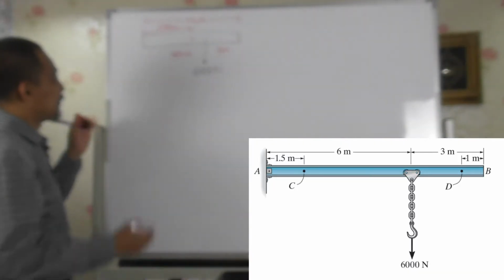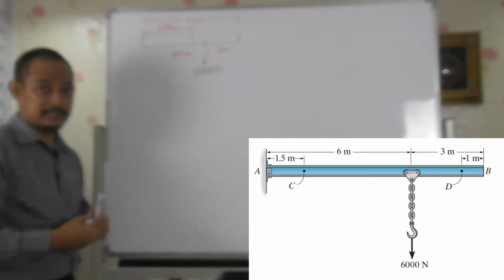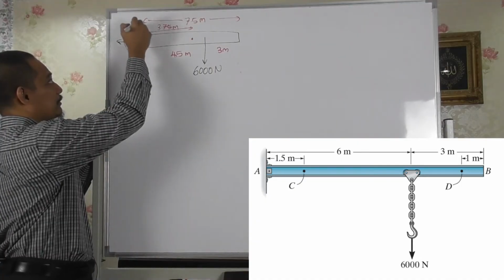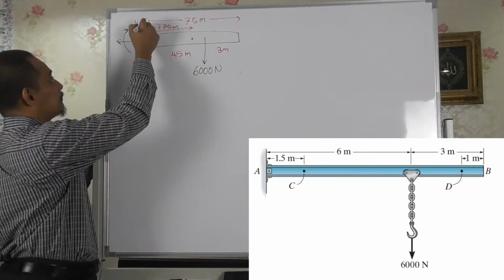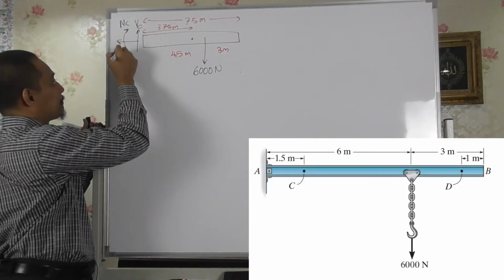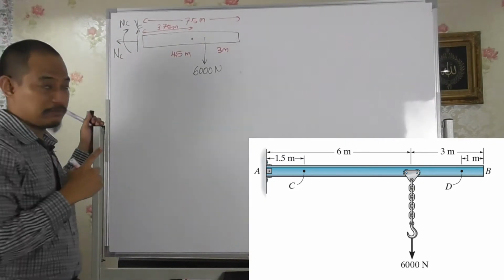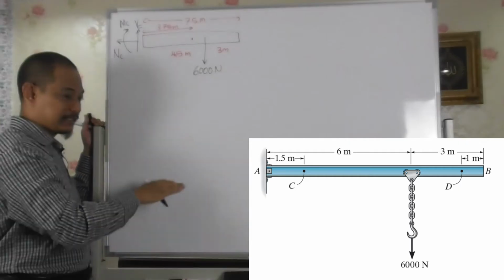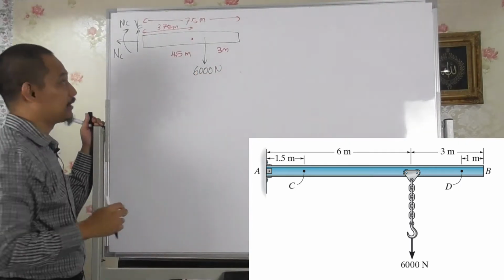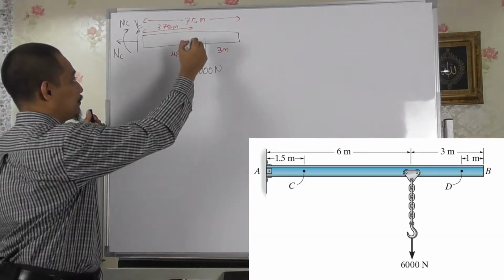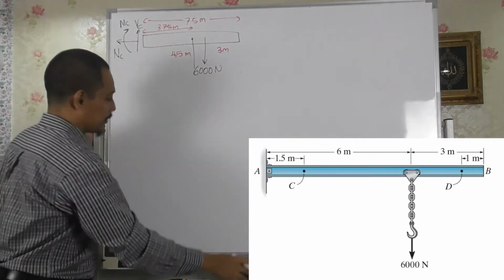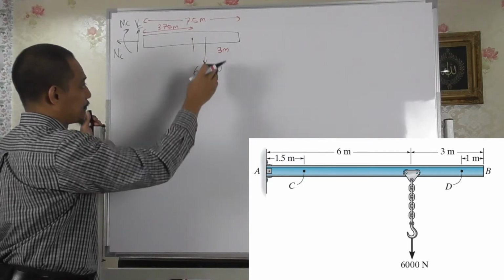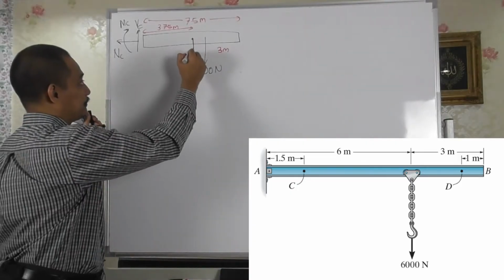Now, we're taking the right side, so we have the normal like this, shear going up and moment going up. This is point C, so VC, MC and NC. That will be your free body diagram. Hopefully everything is clear. Taking the right side, we have to see the dimensions, and there's something missing, which is this load here. Because we don't have enough space, I'll take it here.